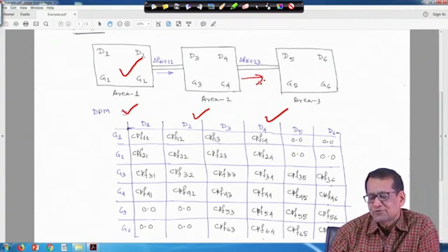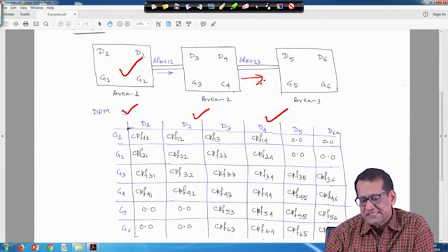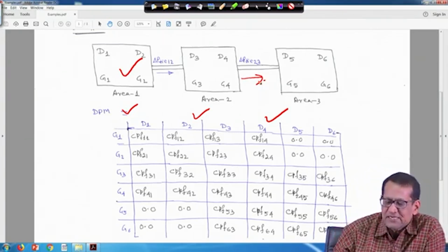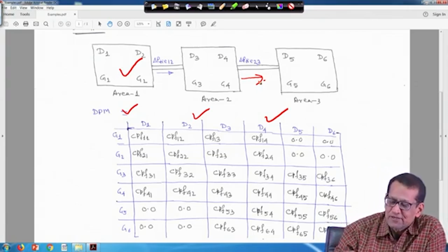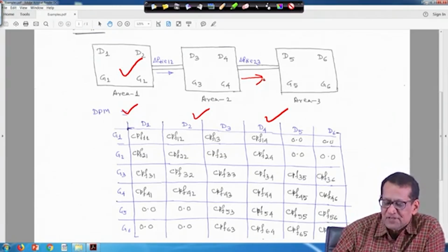power flow is there, say 2 to 3, right. So in this case, your delta p tie 1 2, right, and your delta p tie 2 3. So, first is how to form the DISCO participation matrix.